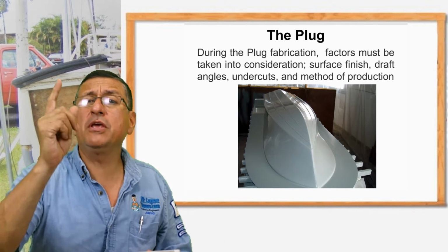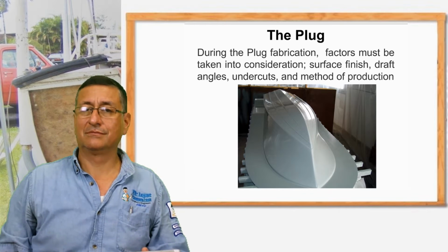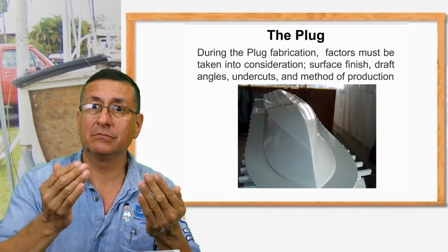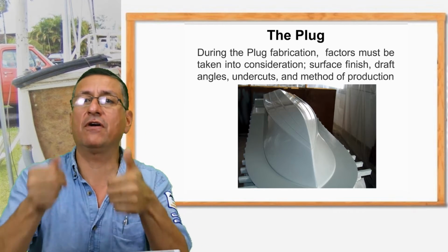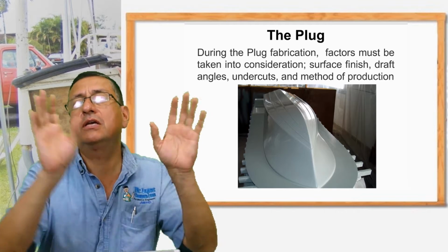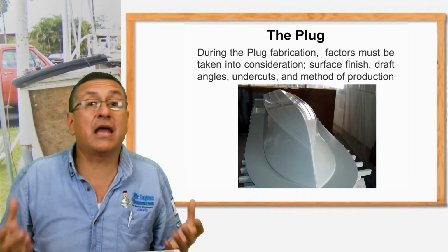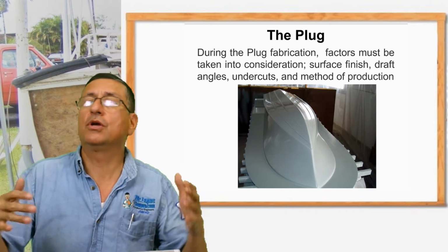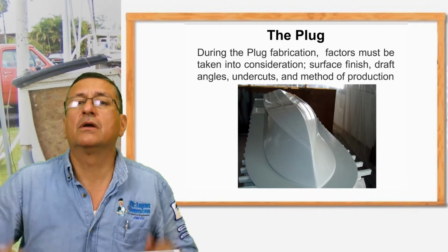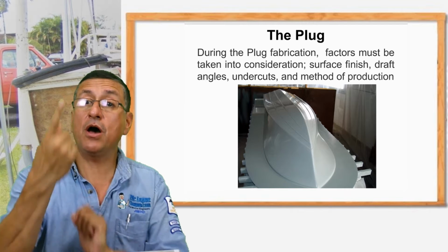The block will be used one time, because with the block I create the mold in high quality resins and fiberglass or carbon fiber. And after that, the block is destroyed, because right now you have the mold, and with the mold you can create hundreds of parts. The block is for one time,